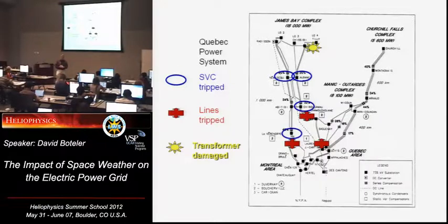Then there's been some transformers, the evidence seems to indicate, that burnt out in South Africa in the aftermath of some magnetic storms. And that was a surprise, and that's still an area that we're investigating, because that's at a lower latitude than we expected to see a lot of problems. But we're trying to see how much it was a case of the system generally being stressed and those transformers being overloaded a lot of the time for normal operation. So it was more a case that the magnetic storm was the straw that broke the camel's back. But that could happen in other countries as well.